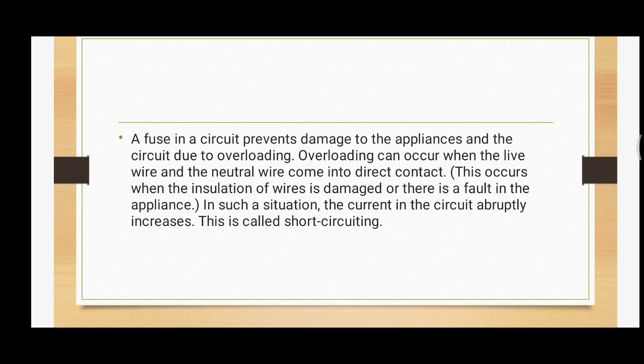As the excess current increases, the resistance increases, and its temperature, that means the heat, increases upon the conducting wire or the fuse wire, and as a result it melts or burns. In such a way, the continuity of the connection will break, and we can save the appliances from excess or high current, or a short circuit like that.